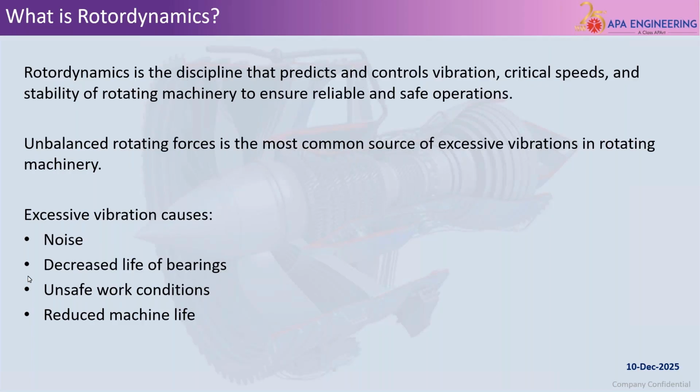One of the most common causes of vibration in rotating machines is unbalanced rotating force. We will look at what unbalanced rotating force is in the next slide. Unbalanced response analysis can be used to predict the critical speed, mode shape, and so on, which can be helpful in accelerating the product development cycle.